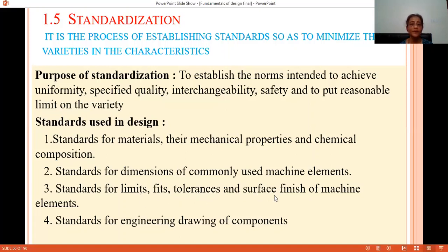We have surface finishing symbols like 2 triangles, 3 triangles, starting from N1, N7, N8 grades. If I say 50H7g6, H is capital. So 50 is the basic size, H is the hole basis system, 7 is the tolerance grade, small g stands for a type of shaft, and 6 is the tolerance grade for the shaft. So the interpretation will be done the same way by everyone.